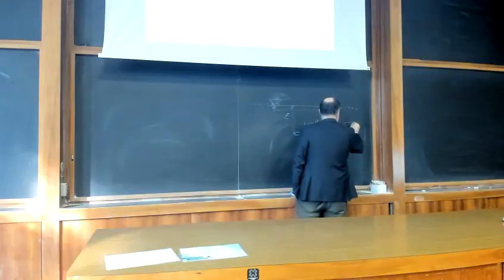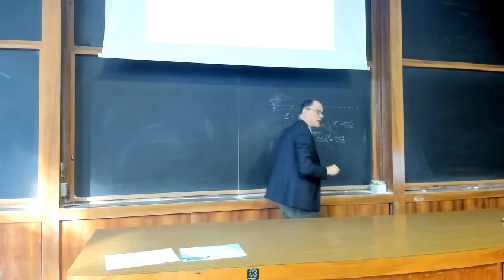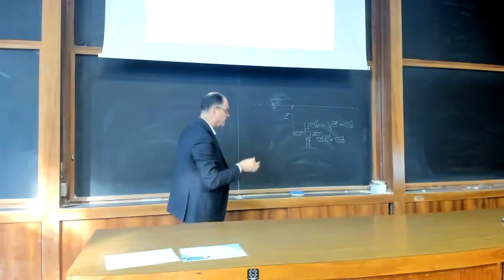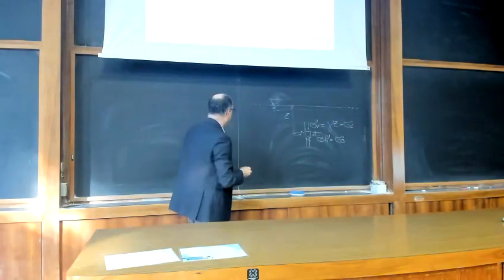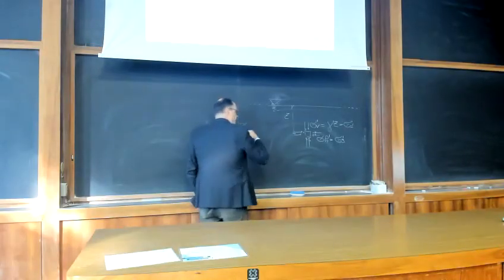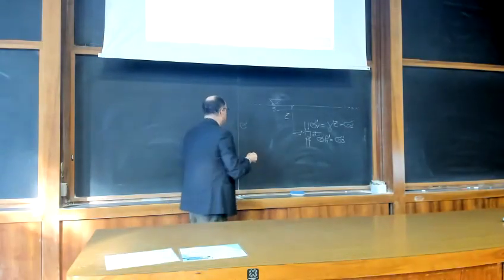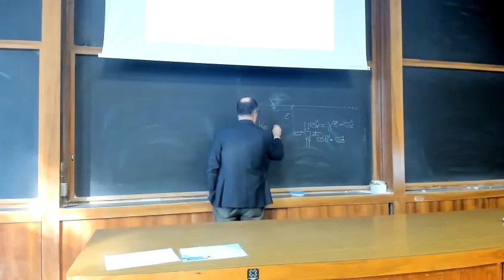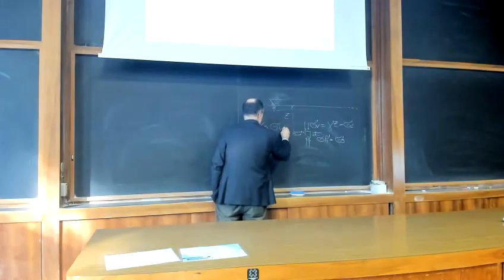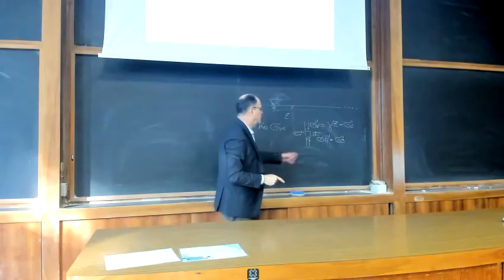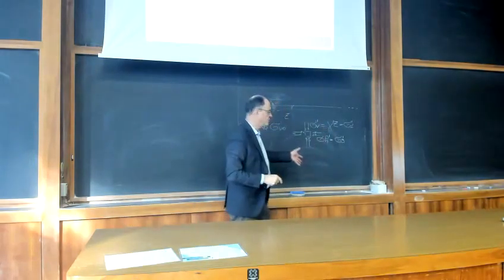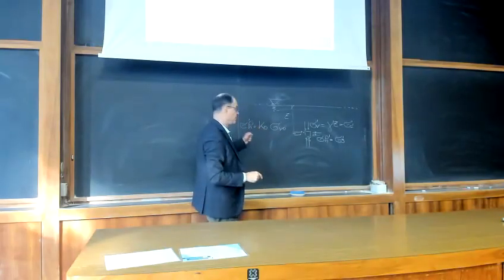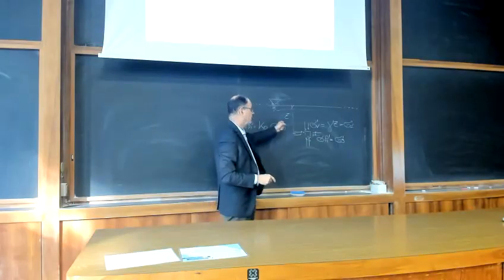Let's always refer to effective stresses. So let's put an apex to all stresses in case there is a difference between effective and total stresses. Now, we have said, also at the beginning of this course, that the horizontal stress can be expressed as a function of an earth pressure coefficient K0. So this is a different way to express the relationship between vertical and horizontal stress. This is valid in terms of effective stresses.